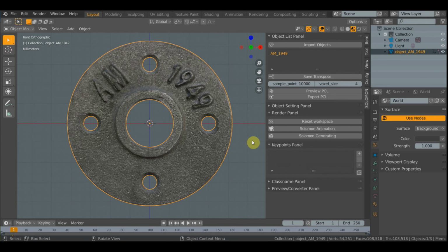The reason why I need to add the key points to the object is that the annotation needs to have the deep learning angle. As you have seen from the tutorial videos of AccuPick and from the manuals, the deep learning angle, known as DL, must be declared to state the correct direction of the X vector of the pick point in AccuPick. Therefore, we need to add 2 points which are going to represent the initial and the last position of the DL angle. Remember that in this example, I only use the X vector of the workspace as a guide to establish the orientation of the DL angle, but in other situations, you can use the DL angle pointing to any direction. Take into account that you can use the same 2 key points for more than one annotation.